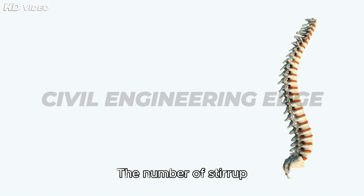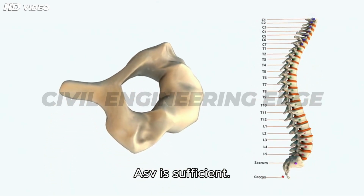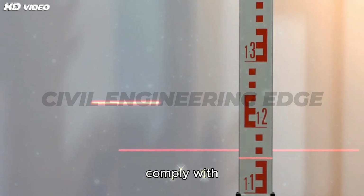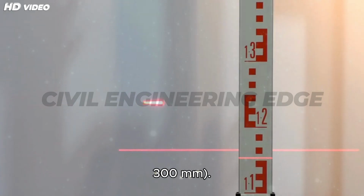The number of stirrup legs and bar diameter is selected to ensure Asv is sufficient. The spacing must also comply with maximum limits: less than or equal to 0.75d or 300 millimeters.